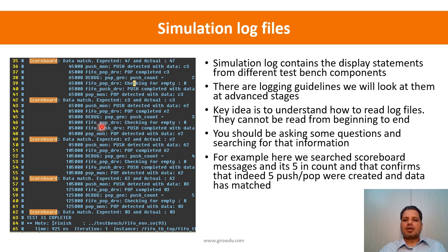Although this is a simple simulation log file where we are just generating 5 push pops and a few hundreds of lines of log are there, you can potentially read it from beginning to end. But there can be log files that consist of lakhs and lakhs of lines, and the log files could be in GBs, and it will take a long time to even just open them up, right? So log files are typically not expected to be read end to end. Instead, what is expected is that you need to ask some questions and extract information from the log file to understand what has happened.